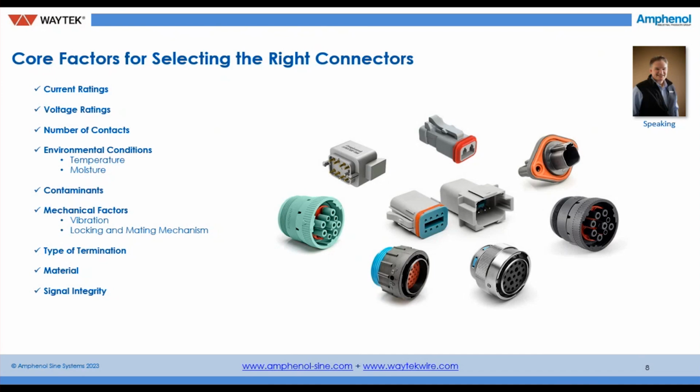Signal integrity, such as contact platings: tin over nickel, silver, gold. Gold comes in a variety of different platings, gold flash, maybe G5, G10, all the way up to G30, also known as heavy gold plating. An interconnect which meets your application's environmental requirements is a must.